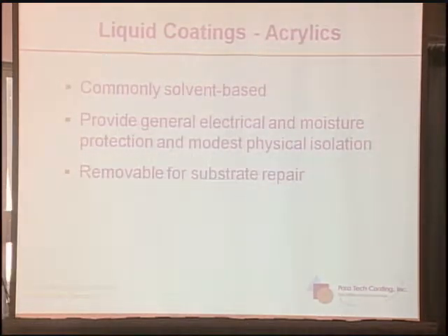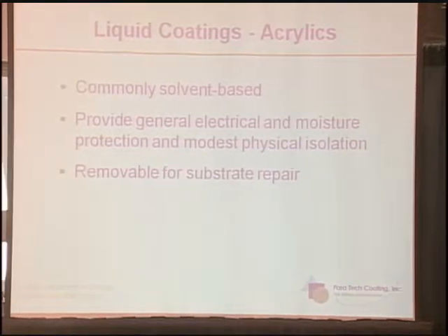The acrylics. They're normally solvent-based, provide general electrical and moisture protection and modest physical isolation, and they're removable for substrate repair. So they're easy to remove. That's a consideration you might want to take a look at, and it depends again on your application.